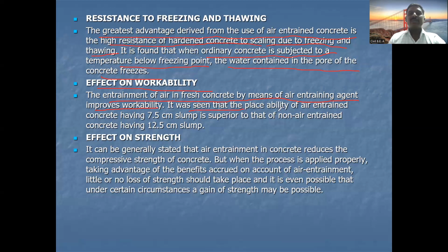It was seen that the placeability of air entrained concrete having a 7.5 centimeter slump is superior to that of non-entrained concrete having a 12.5 centimeter slump. So if the air entrained concrete has a slump of 7.5 centimeter, the non-entrained concrete will have a slump of 12.5 centimeter. So this is the effect on workability also.